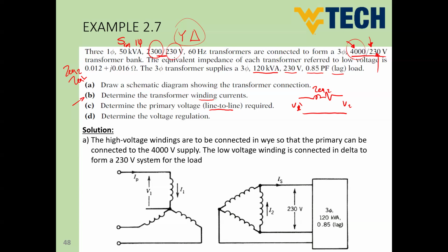So this means the three-phase connection of this transformer can support up to 3 times 50 kVA, which is 150 kVA. So this transformer can be loaded by 150 kVA. However, this doesn't mean our load is going to absorb this amount of power. It depends on how much load we are supplying from this transformer. Okay, but the capacity of the transformer is 150 kVA.